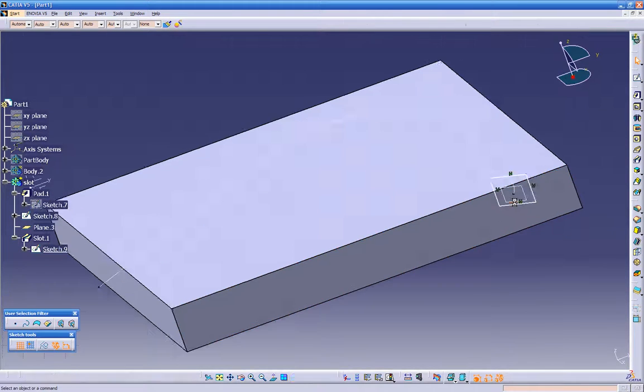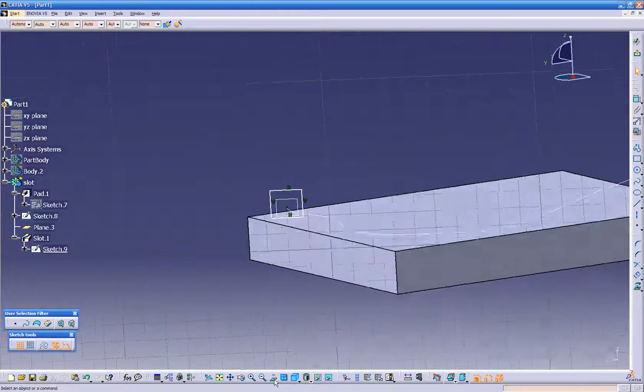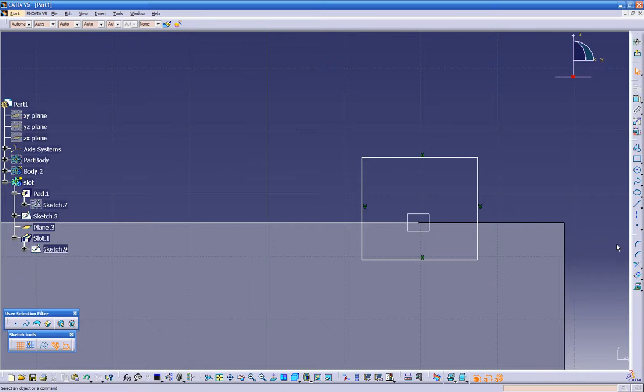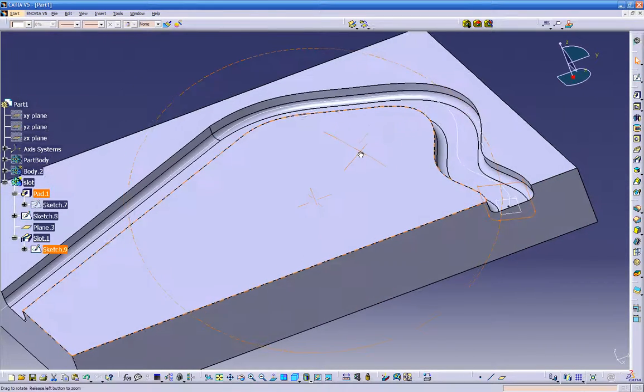We can double click on our sketch, go back on our sketch. Let's click this normal to view twice, and we can have our radius over here, and we can just highlight this, click corner radius, 0.100, and get out of here, and we have our fillets in there.